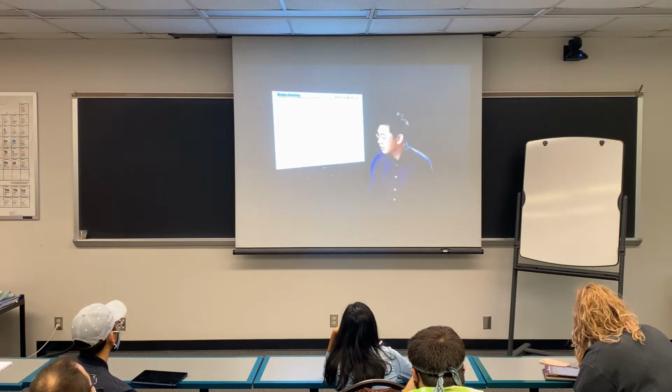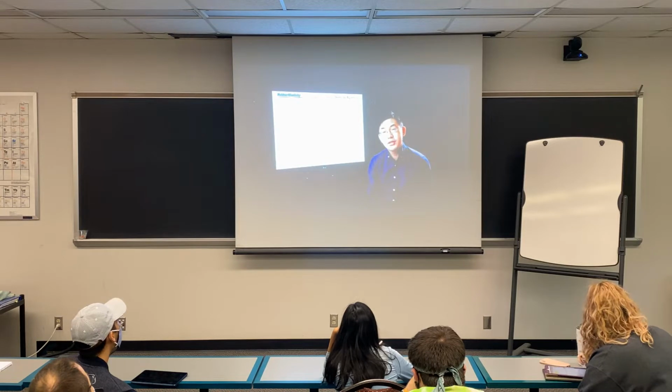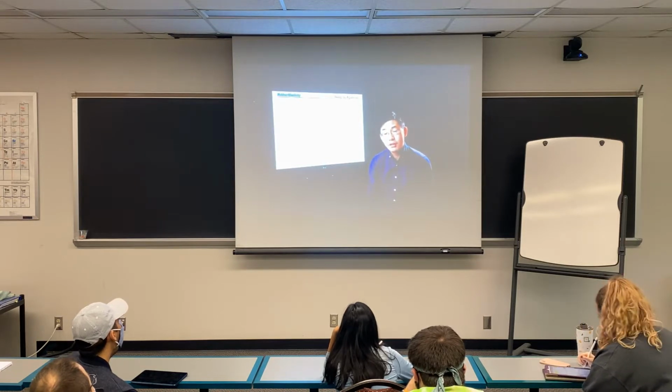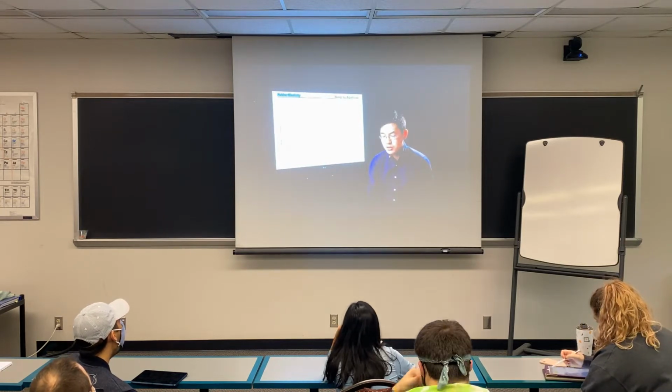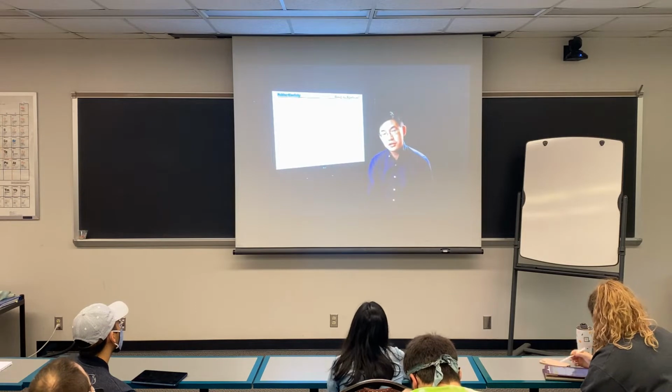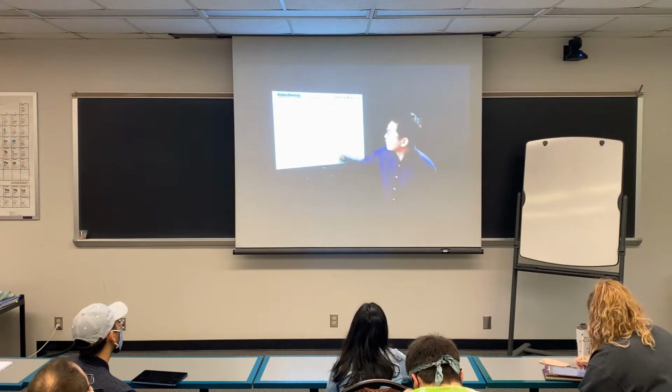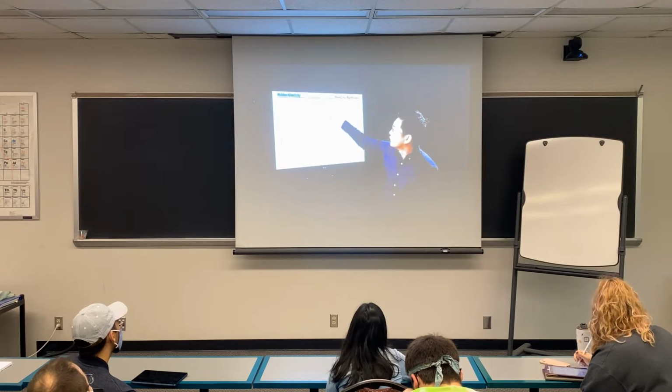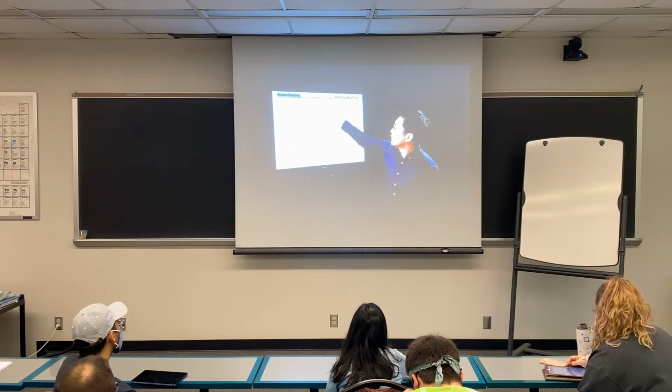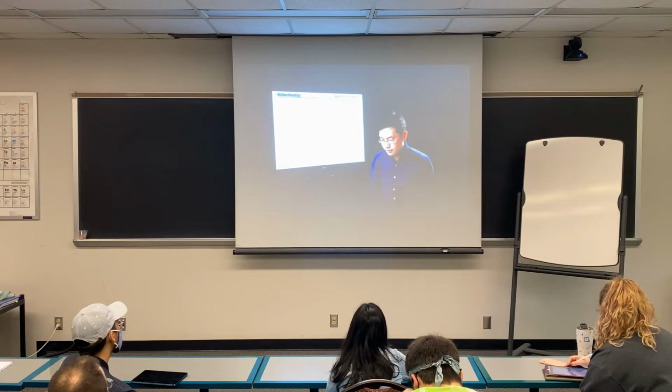But if you watch carefully, in the compression region it is very good. However, in the tensile, or extension, region your data start to deviate more and more at a higher degree of strain. So look here: when your strain is 2.0, there is a much bigger difference.